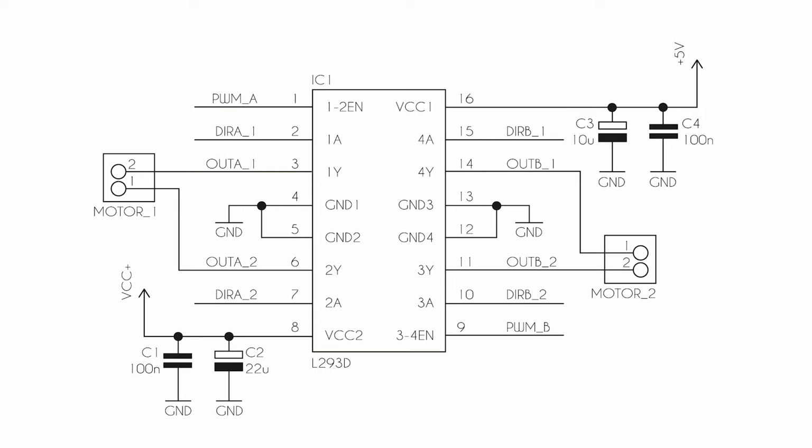Let us take care of one of the most basic drivers, the L293. It contains 4 half bridges capable of transmitting 1 ampere of current per half bridge. The version with the letter D at its end contains the protective diodes in its structure and can transmit up to 600 mA of current. It has control inputs marked with a half bridge number and the letter A. The outputs of the half bridges are analogous outputs with the letters Y. The inputs 12EN and 34EN turn off the half bridges with the numbers shown.